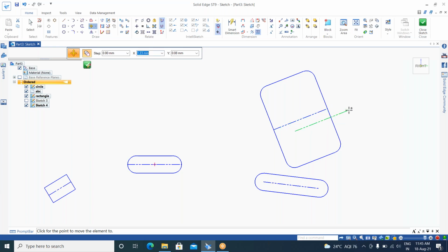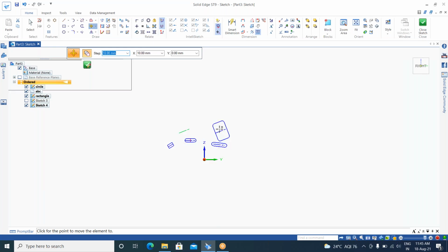So this is my center point. So how many objects are needed? I can directly take my distance from one object to another object. For example, I'm going to give 10 mm. Okay, this step means for every 10 mm it will show. See, from here to here 10 mm, next 10 mm, next, for every 10 mm in incremental manner it will indicate to us.